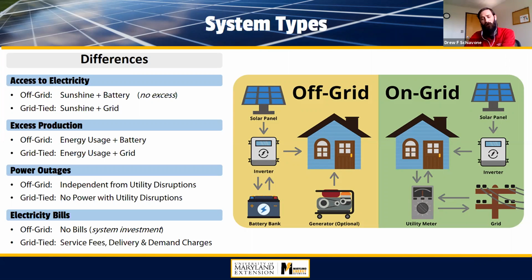And so you'll be without utility and without solar, and that's a safety feature that's required by law, that your PV system is deactivated so you're not backfeeding energy onto the lines, which poses a significant risk to anyone working on the system. So just to reemphasize that.